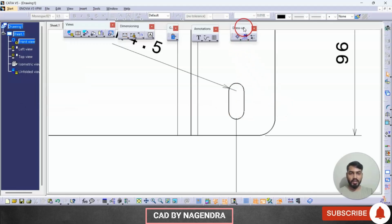So to create that, under dress up, we can go here, center axis line between this to this. Exactly one center line it will create. But we need a horizontal one. So we'll click here. Let me select these two circles. Vertical only we are able to get, horizontal we are not able to get. So no problem. This to this also, if you create like this, it will come.